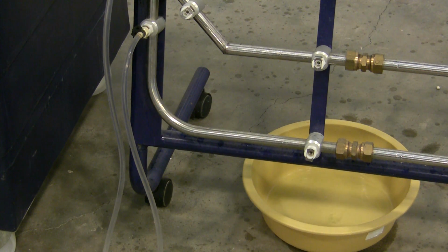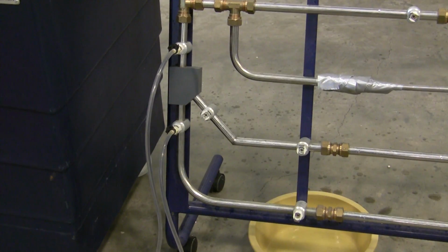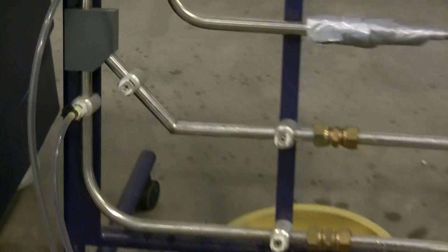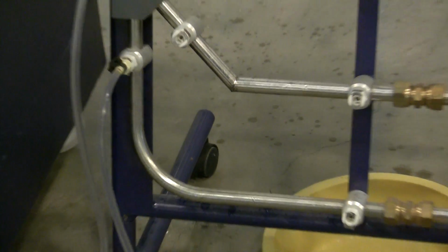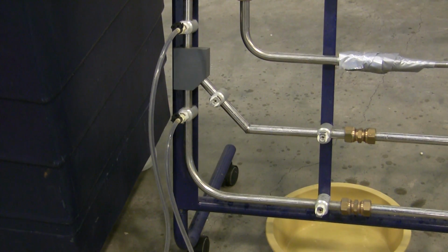Rather than unplugging the tap that I've already got in at the lower position, I'm just going to unplug the upper one that's here and move it to this location. Now, swapping what's the upstream and the downstream is going to mean that I'm going to have positive pressures now instead of negative, but that's okay. We still know it's a pressure drop. Let me go ahead and do that.